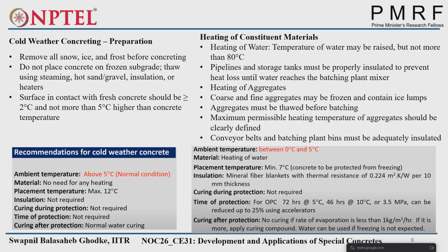Water can be used if freezing is not expected. Based on the weather condition, if freezing is not expected, we can go for water curing. Otherwise, we can go with membrane curing, or spray any type of curing compound on the surface, which will prevent evaporation of water from the surface to the weather and will cover that surface as well.